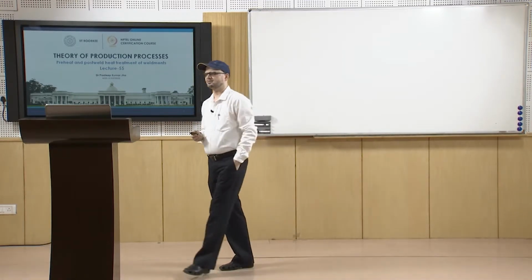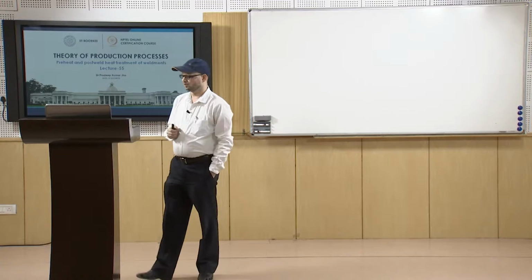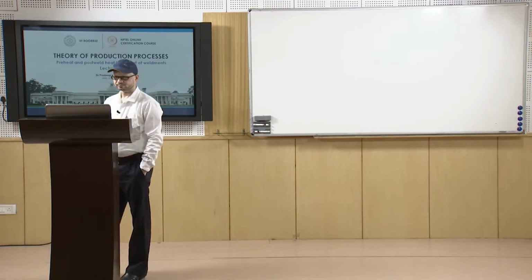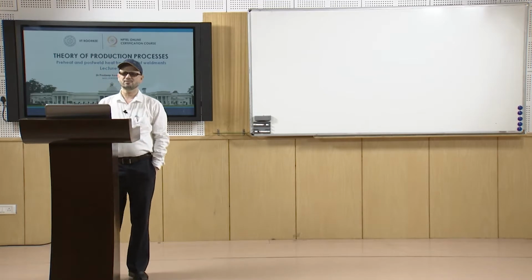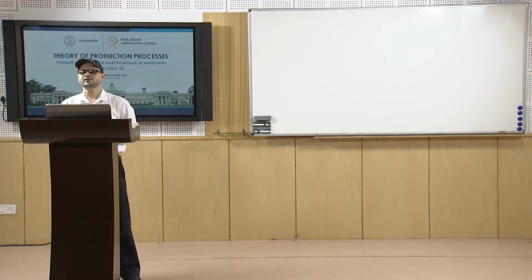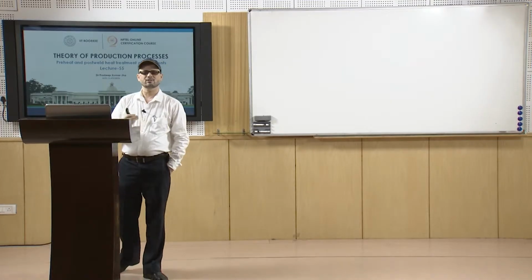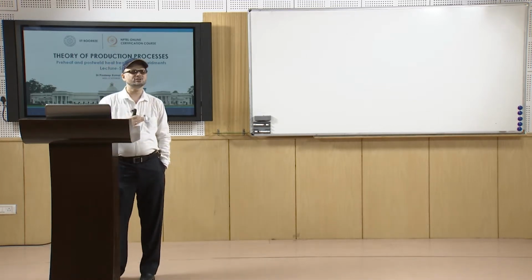Now, we will discuss the preheat temperature of different materials. Among the materials, suppose we discuss carbon steel. In the case of carbon steel, preheating is necessary for heavy sections. When the carbon content is smaller, you do not require that much preheating, because the hardenability is less.